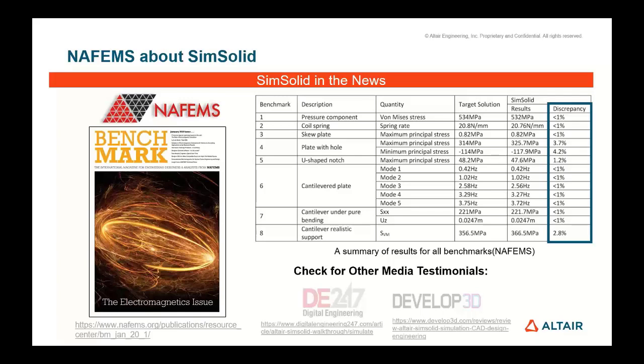Okay, and then about SimSolid, let's say we import an assembly from SolidWorks or CATIA, just fixed in space parts won't work, so each and every component has to have constraint or mate features? Not sure if I get that. Let me try. If I understood that correctly, if you're importing a whole assembly, just fixed in space parts won't work. What I understand is, do we need to define additional constraints on each component?